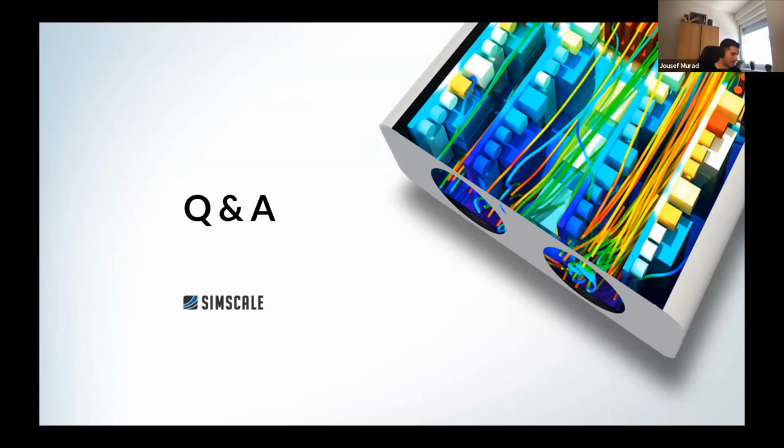Ravi Khan, thank you so much for the question. He asked how SimScale is associated with OpenFOAM. So for CFD, OpenFOAM is running in the background, but you have to pay attention. It's not OpenFOAM per se, in the sense that it's not simply a copy of what you can download. Our developers have made plenty of changes to that OpenFOAM version. So it's kind of OpenFOAM, but also not OpenFOAM, if you get what I mean. It was drastically changed in terms of how the code performs. The CHT solver, for example, was also changed drastically. We have a CHT V2 solver, which is way more performant and way faster than it was before.